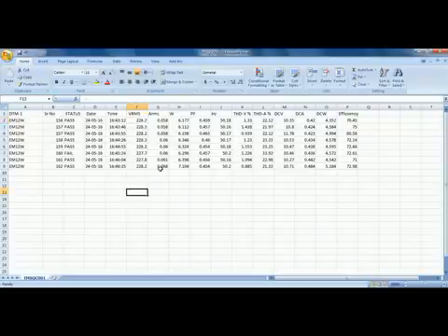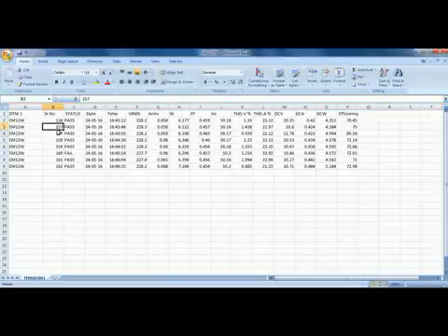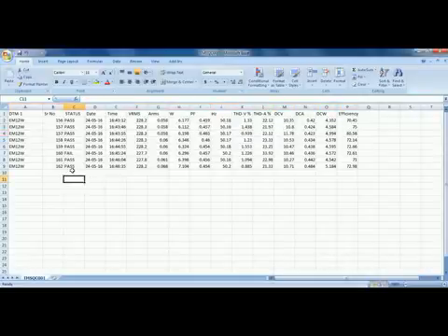Now one of the lines is showing fail. This one is showing fail, apparently because the THD current was more than 30%. Also you can see that all this data has been logged automatically without pressing a button, and at one point the person had pressed the button, so he got another entry, one more entry. So if you want one more entry, you can press the button also.